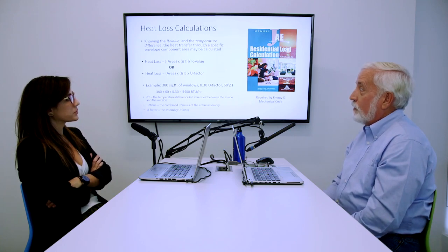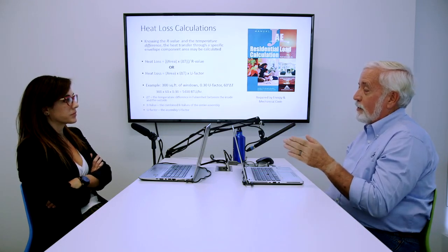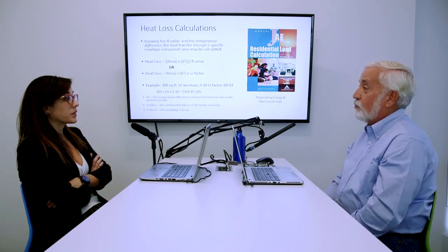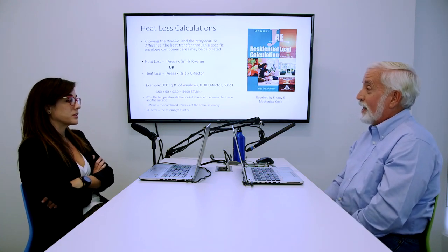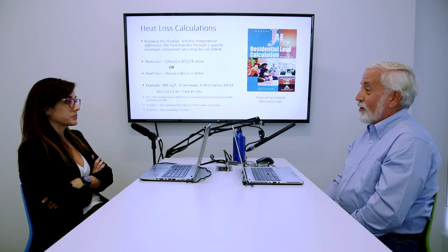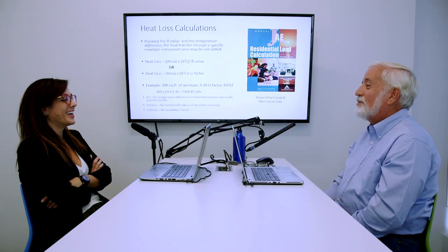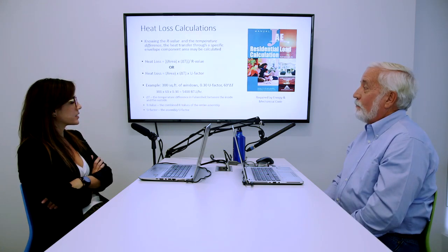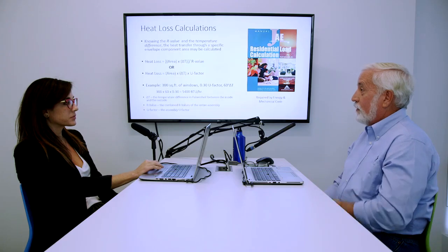We are seeing AMSCO makes a double coat window, and so they have coatings on both the outer pane and the inner pane. And with that, we're seeing windows with just 2 panes of glass coming in at 0.28 and 0.27, which is really good for 2 panes of glass. If someone had submitted that 7 years ago on a REScheck and said that I have 0.27 windows, I would have told them, no, you don't. Show me. So that's really good, and doing it with just 2 panes of glass instead of the third, which gets really expensive.